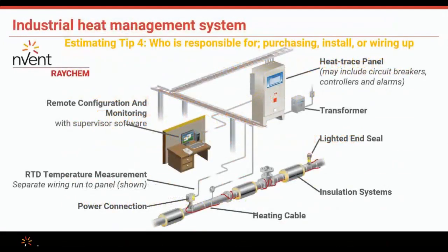All right, estimating tip number 4. So who is responsible for purchasing this? Who's responsible for the installation or the wiring of this? There's a lot of parts and pieces and components to this heat trace system. And you have to be cognizant of where it's called out in the spec, and what their notes say in a project that's a designed project. So be sure to ask those questions.